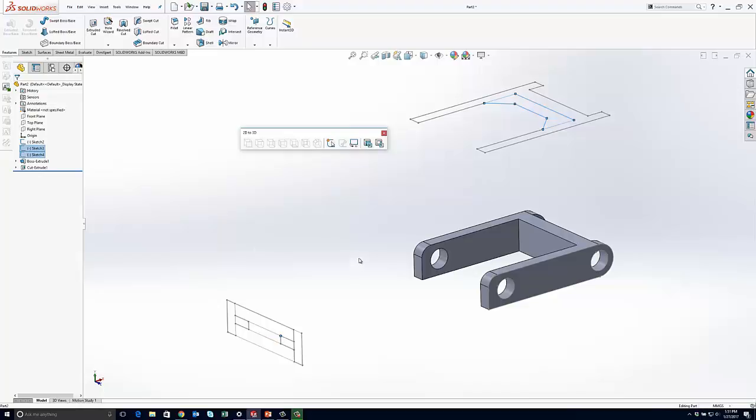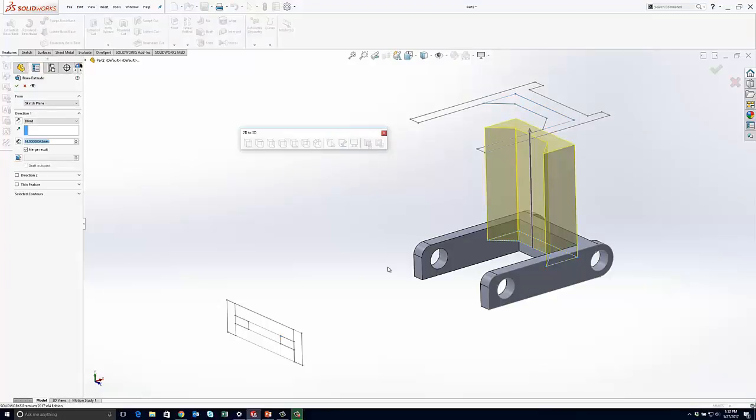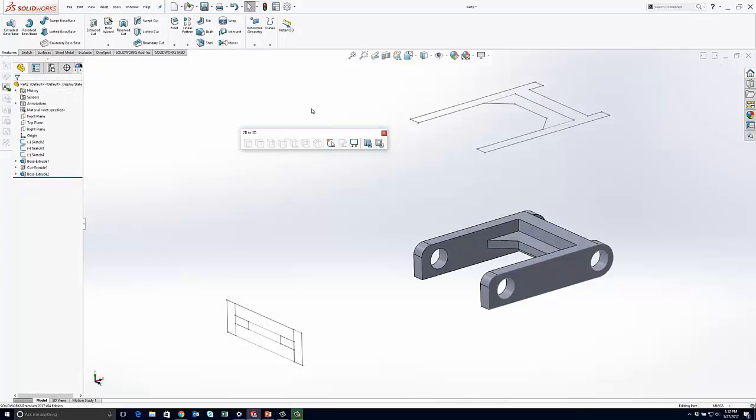Now that I've got everything selected that I want, I'm going to tell this to go ahead and convert to an extrusion. Now you can see that what that does for us is it allows our extrusion to actually start at a different plane or a different level there. So we'll go ahead and use our depth once again, pick our entity, and we can see once again after about the 6th or 7th decimal place we trail off and have a little bit off in our dimension. We'll just go ahead and accept it the way it is, and that builds our part for us.